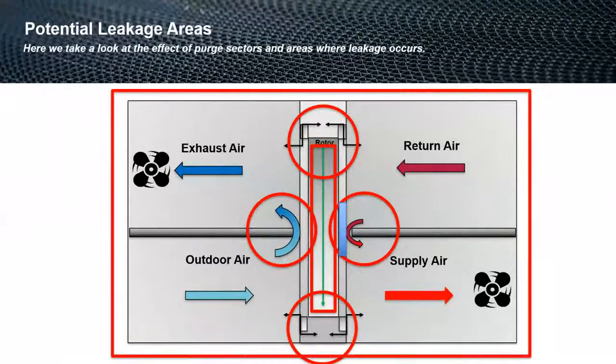But there's also the leakage of the entire case of the air handling unit to take into consideration. So when we say leakage of the case and how critical that could be, if we had a plant room with 4 air handling units in the plant room, and let's say, for example, it's a hospital and one of the air handling units is taking extract air from the mortuary or some other place that's critical within the building, if the case of the air handling unit is leaking, then there is a chance that some of the other units close by could take that air in from that space as well.